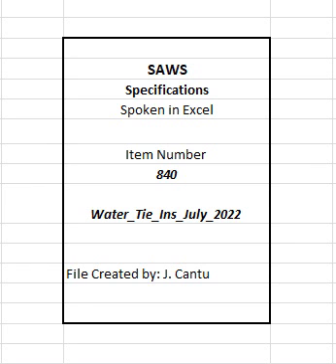4. The planned shutdown, tie-in work, and hours shall be coordinated through and approved by the SAWS inspector. The contractor is required to provide written notification to the SAWS inspector at least 25 calendar days in advance of the anticipated tie-in date for customer coordination and test shutdowns. The shutdowns shall be accomplished at a time that results in the least inconvenience to SAWS customers, including overnight shutdowns at no additional cost to SAWS.